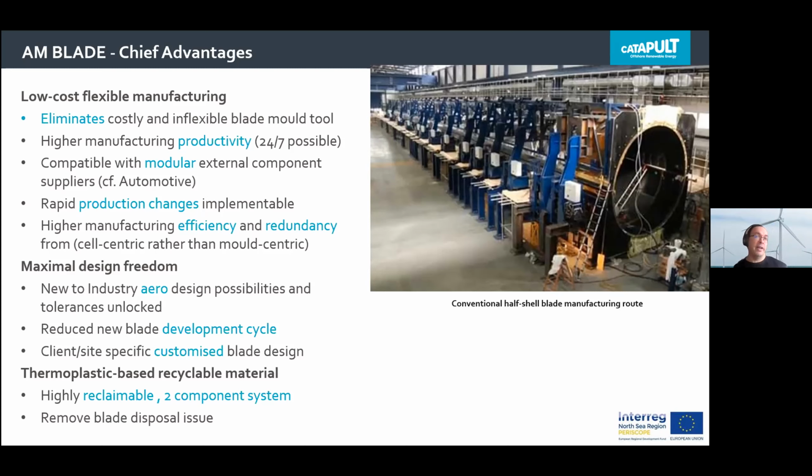And lastly, of course, I know I've mentioned before, it's very important that the material system that we've discussed, that we're looking to use from this concept study, is basically a two-component system. So inherently, it means there's no mixed waste stream, so it's far easier to recycle, and that's the ultimate aim. So you're having one fiber type, maybe two fiber types, but basically one matrix system to replace a lot of adhesive and metallic structures, or where we can avoid metallic structures. Obviously, for things like lightning protection, we'll still need those metal components, but it'll be basically to a bare minimum.